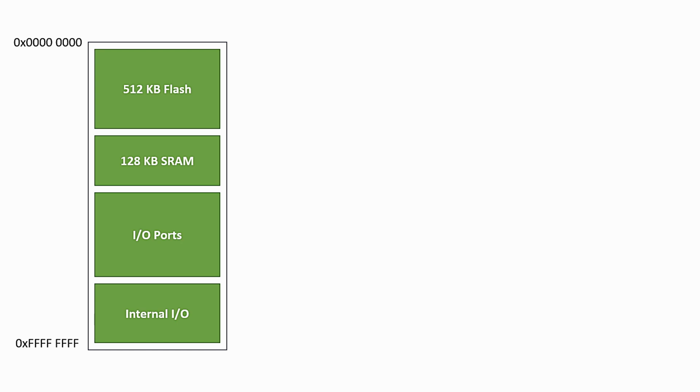And within this region, from the datasheet of the microcontroller STM32F446RE, the RAM address starts from 0x20000000 to 0x2001FFFF. So here it is wrong, it is actually 1FFFF, which means the total size of RAM is 128 KB.